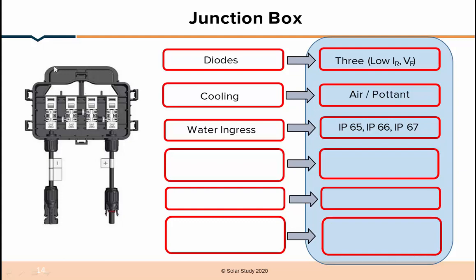So you can see this junction box contains two terminals, 1 and 2, and it is protected by the diode. This is called a diode in the junction box, or anti-parallel diode. I will tell you why this anti-parallel diode is required.